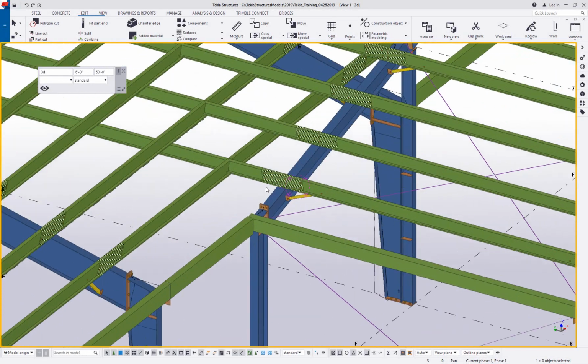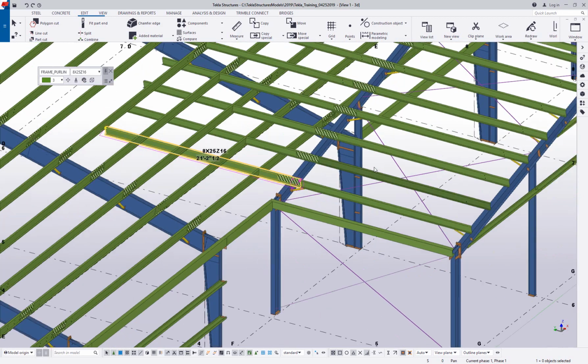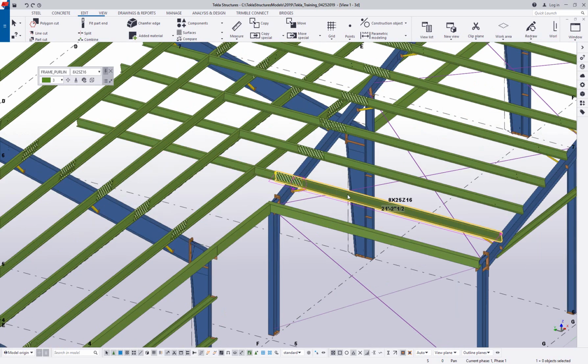In this example, we can see that the entry building was designed with some bypass purlins so that we could extend out the roof to meet up with the main building roof. However, what we might be able to do instead of the bypass purlins is simply extend the shorter pieces out until they frame together. Remember that for best results and minimal cleanup, you want to make sure that entry building has its purlins set up with a spacing so that they align with the main building purlins.